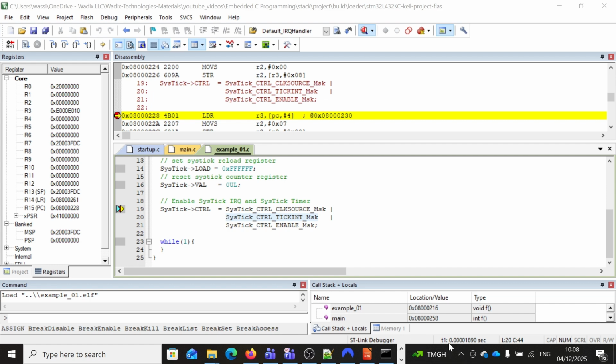So the stack pointer, after we get this interrupt context switching, the processor will force it to be 8 bytes aligned. And if it is not the case, then beside the CPU registers to be saved, it may append certain bytes to preserve this 8 bytes alignment.